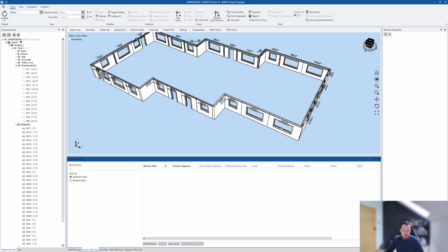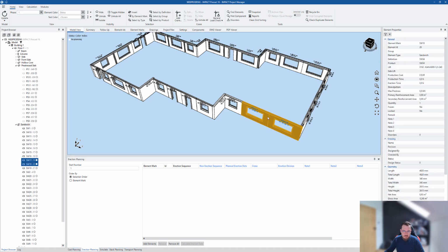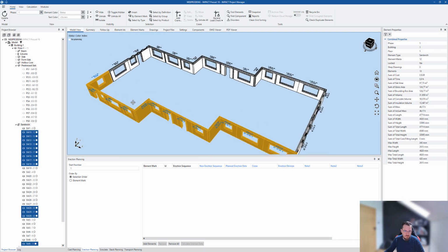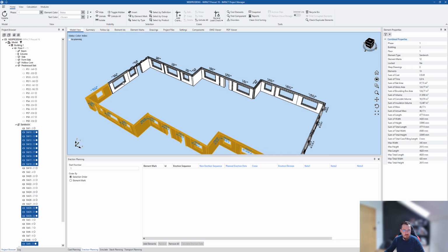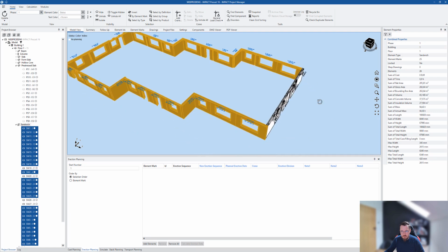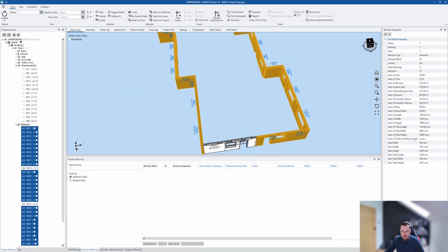So that's useful, as mentioned, in order to properly create stacks of elements. You can either hold control on your keyboard and left click on the elements like so, one by one, or you can just hold shift as well along with control, and then you'll get this nice line. Basically the order in which the line crosses the elements is the order the elements will be erected, which I'll demonstrate that shortly. Right, click, click, click, click,